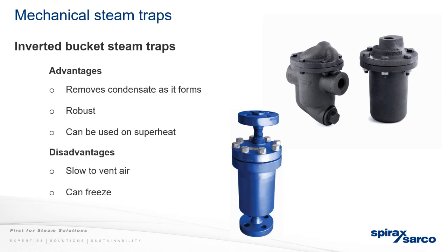Another question has just come up, Nick: is there any maintenance that you can do on these traps, the mechanical traps? Yeah, of course. So us, as well as other manufacturers, we sell the spares for the traps. So it's not a case of having to replace the whole thing every single time. What we have is a maintenance kit, so expected bits we believe will wear. But there's pretty much everything inside that trap you can buy and replace.